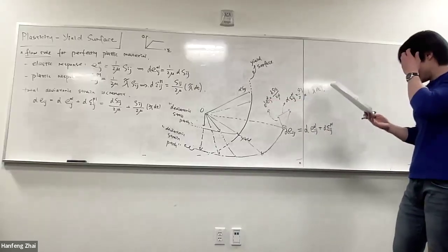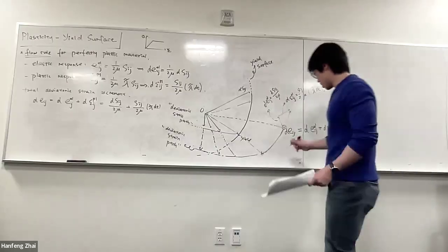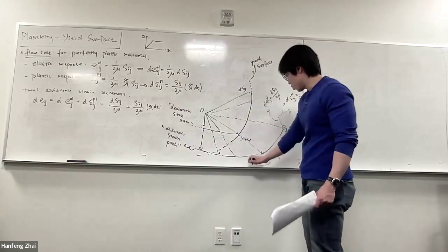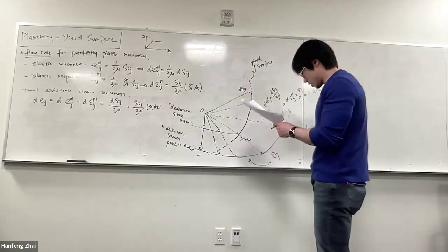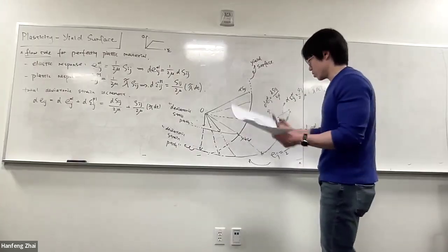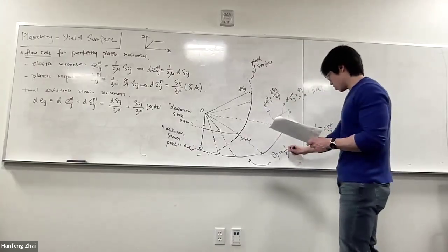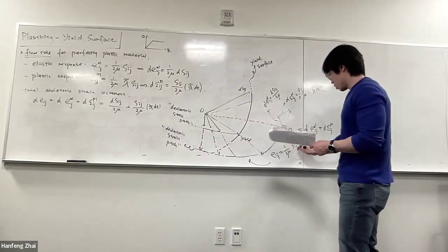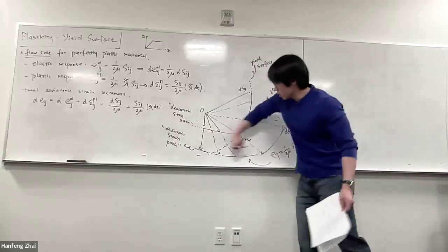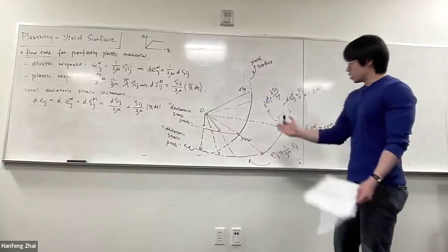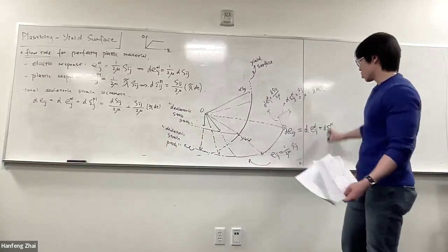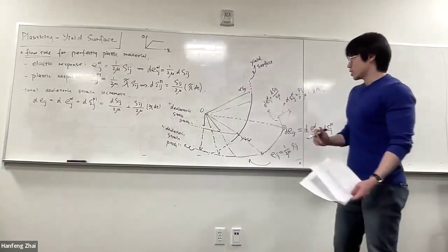All right, cool. And just one thing that we always keep in mind: e_ij before you reach the yield point, in the elastic regime, follows the elastic response. So it's 1 over 2 mu, shear modulus, correlated with the deviatoric stress component. There's e_ij and S_ij correlation in the elastic regime, and once you reach the yield point, the strain propagates or steps forward according to the fundamental equation of plasticity.